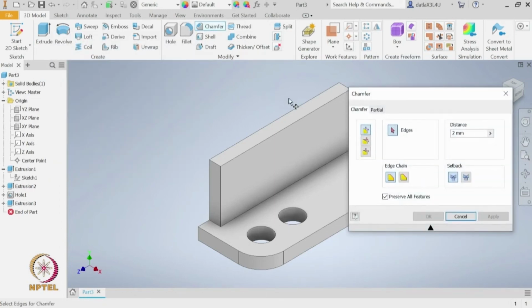For the chamfer, again it is asking three options, whether it is equal distance, or do you want to specify a distance and an angle, or both distances. So, let us click the first option because it is single distance on both sides, which is 45. Now, I need to click the edge where we want to have the chamfer. Okay. So, this is the preview, that looks okay. So, let us press OK.